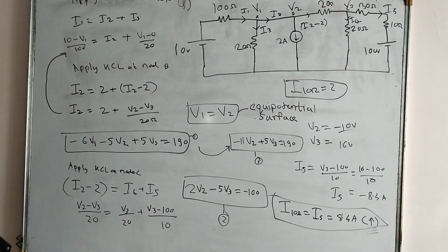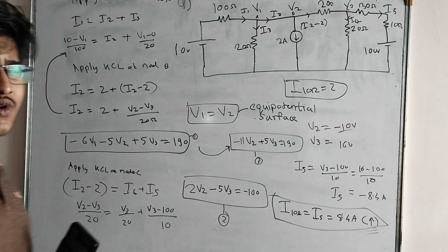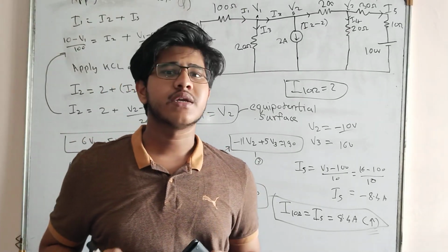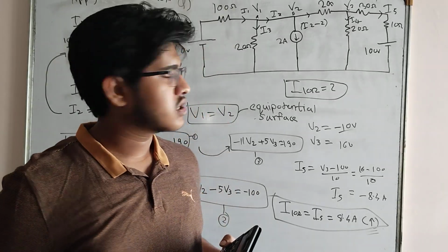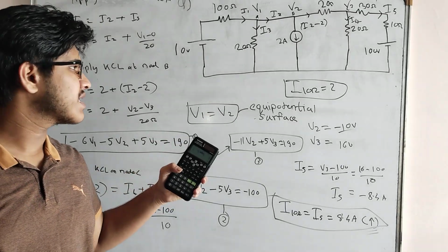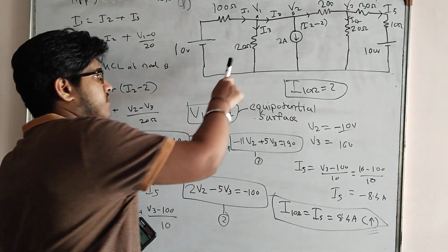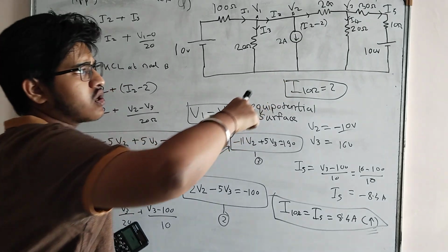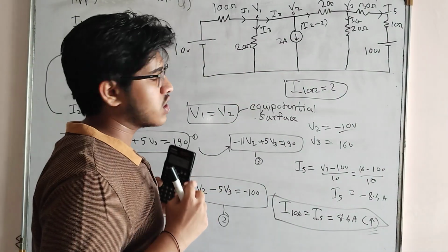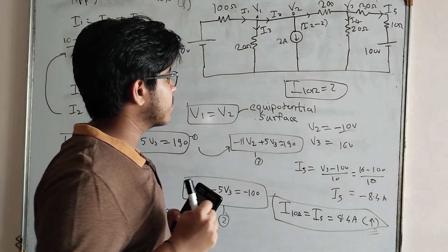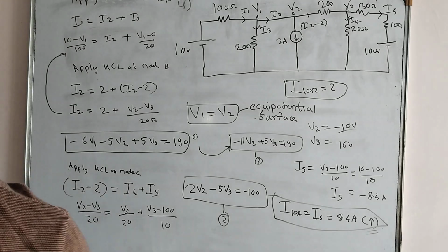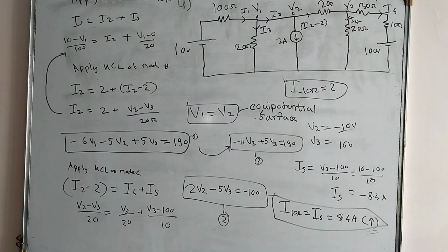Okay, so you can note down the question. Now I will give you one more question as your homework, and I will also mention its answer, but the process is yours. You can also solve this question with mesh analysis, but you will get 4 unknown equations, or you can use a source transformation and convert it into a question having 3 meshes with 3 unknown currents, and you can simply solve it that way also. So please note this down.